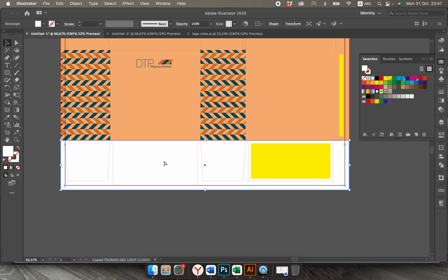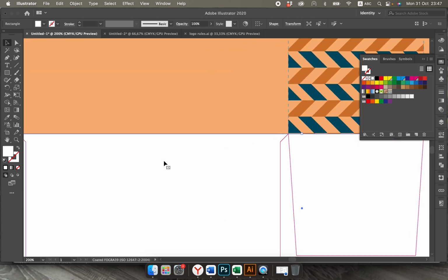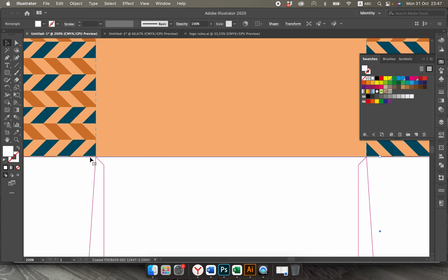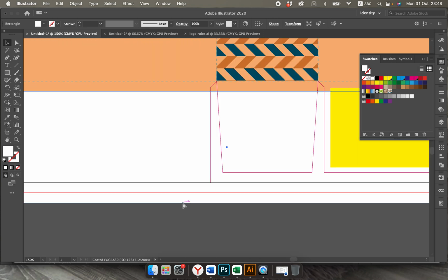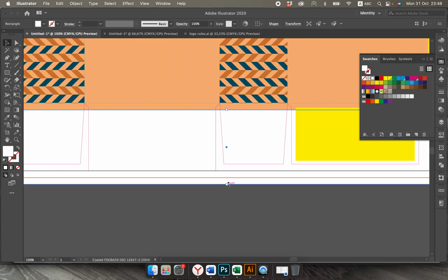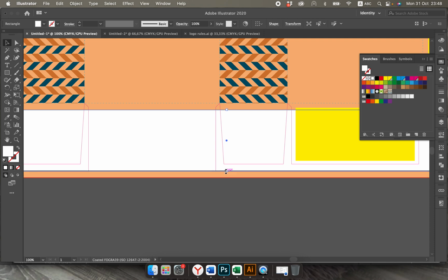So now one more thing, because when we make a fold line of the package here, probably we could get some white space when we fold it not exactly on the line which we need. In this case, it's better to move our element down about 3 millimeters. 1, 2, 3, 4, 5. Usually it goes according to the bleed options. And now I can move it exactly to the place where I need.